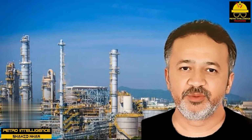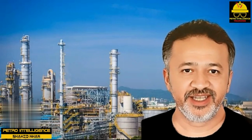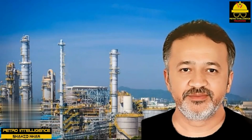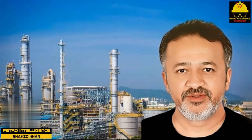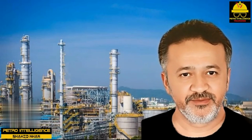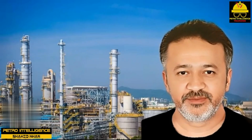2. Uneven vapor flow bubbling up through the tray deck will promote vapor-liquid channeling. This sort of channeling accounts for many trays that fail to fractionate up to expectations. To understand the cause of this channeling, we will have to quantify total tray pressure drop. Tray pressure drop.